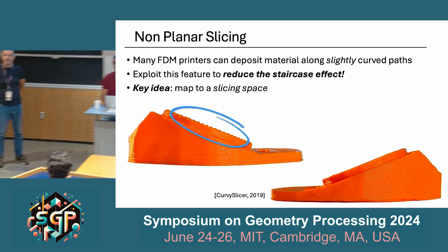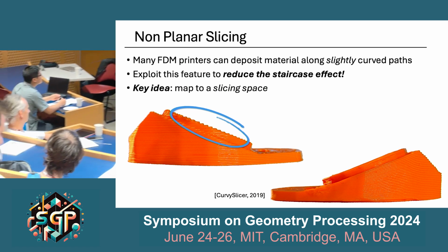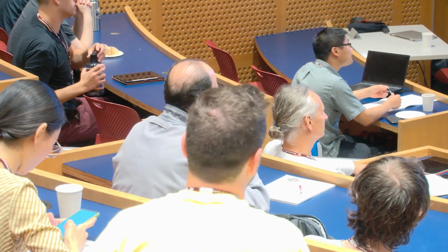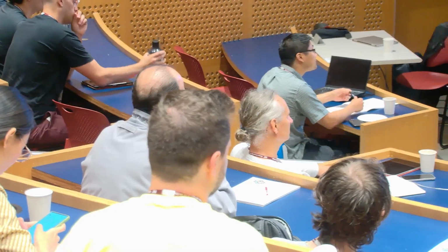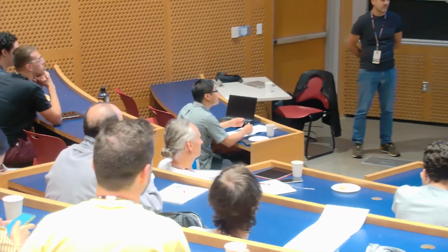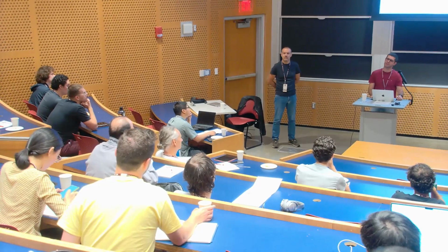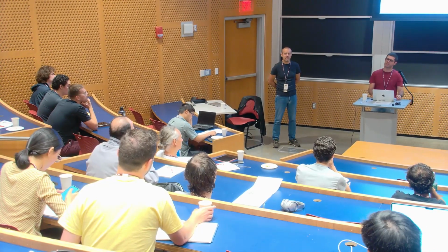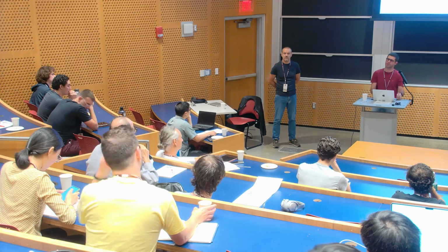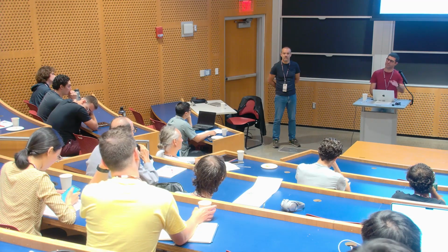With stereolithography, is it my imagination, or were there systems that used multiple laser beams to pinpoint? Well, there are many different fashions. The one that I talked about has a UV projector that projects a binary image, which is going to be like a thick voxel, this is part of the object, non-thick voxel, this is outside of the object.